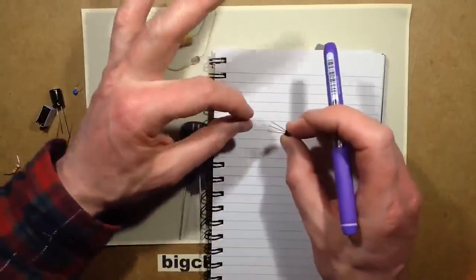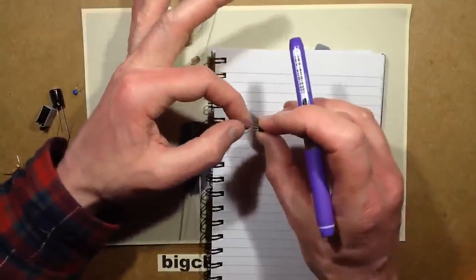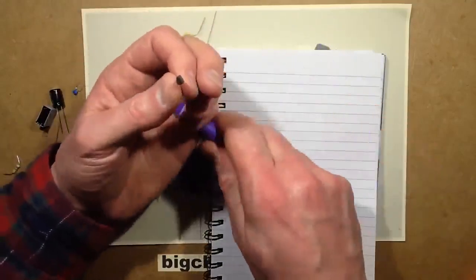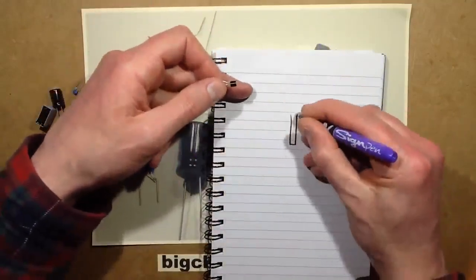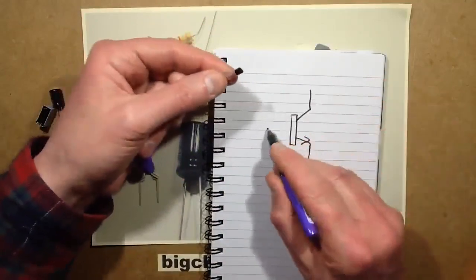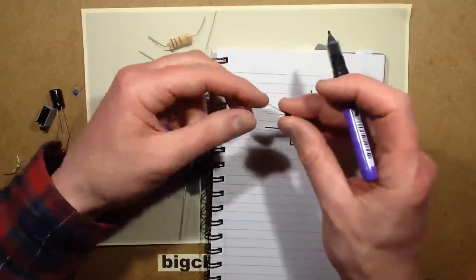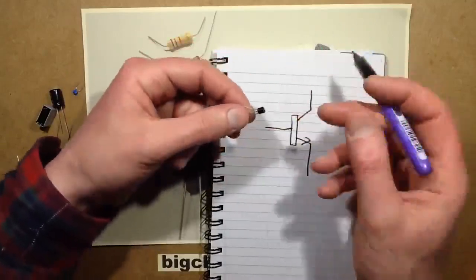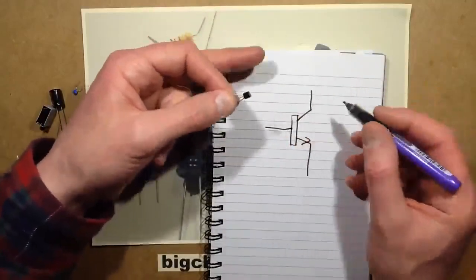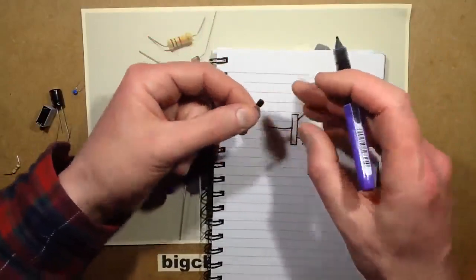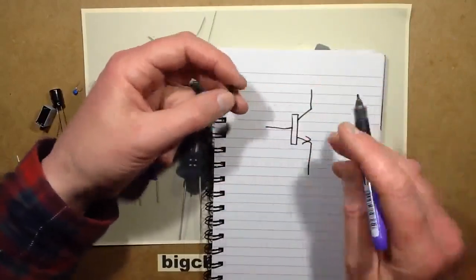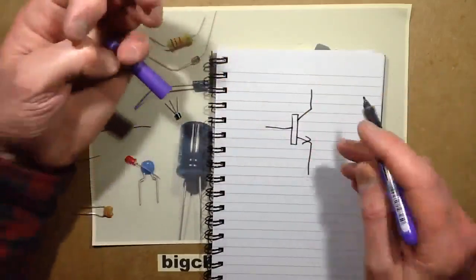For simplicity, I'm just going to show the basic NPN silicon transistor, one of the oldest fashioned type transistors about. And the symbol for it is this. You get 3 pins, and if you ever want to find out what the pinout for your transistor is, if you're not 100% sure, just go on Google and type its number in, like 2N3904. Google it, look for images, and you'll find pictures of the transistor with the actual pin designations printed under them. It just makes it very easy to find data like that.